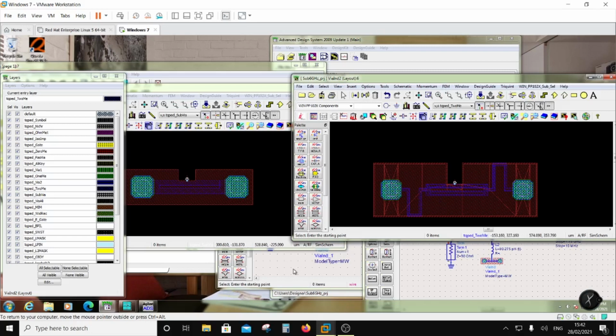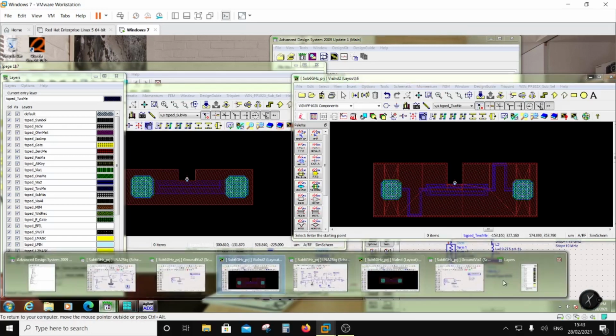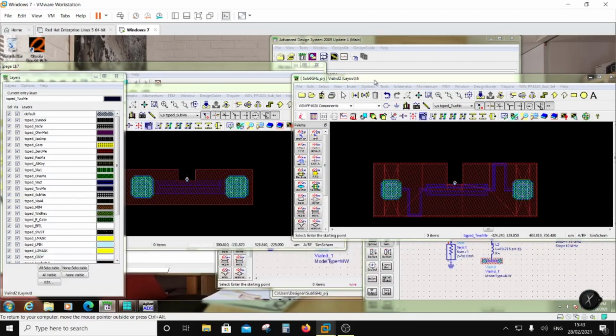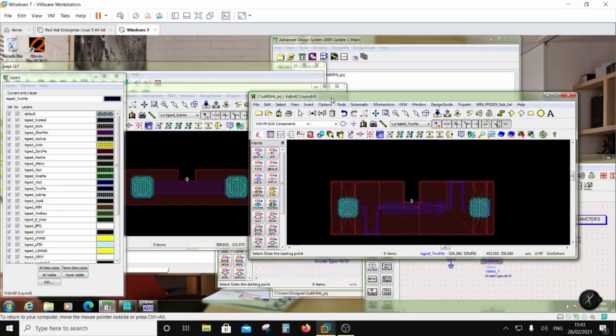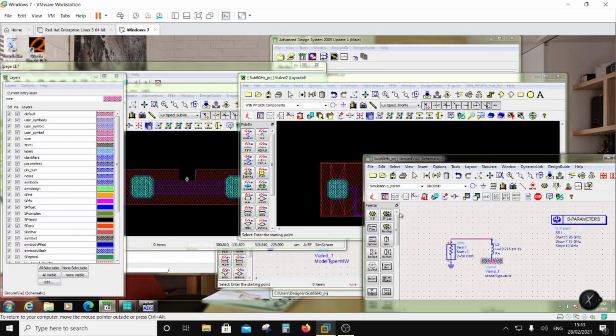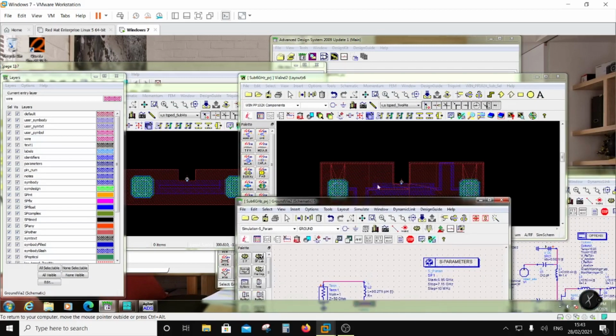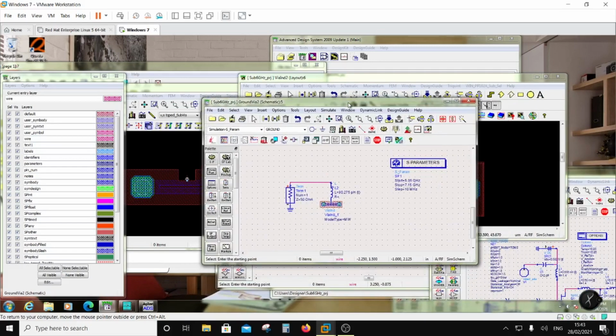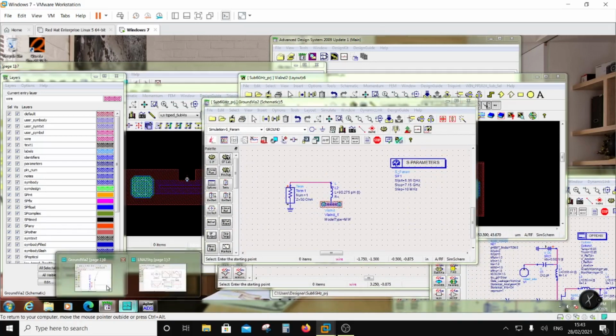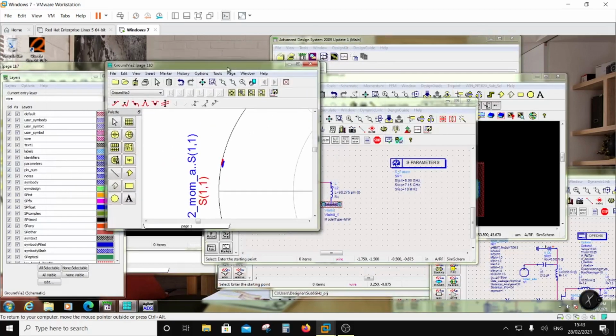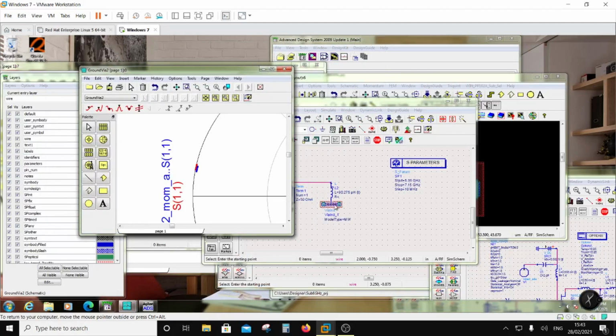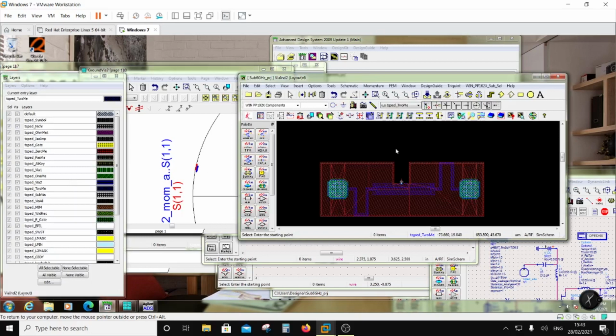So once I do that, then what do I have? Okay, so once I do that, I can compare the circuit simulation with the response from the EM simulation, and this looks like this. So the red one is basically this EM plus 90 picohenry circuit, while the blue one is where the 90 picohenry has been absorbed as these two meander lines, right?